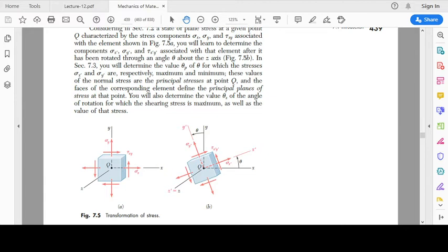In chapter 2 we talked about axial loading, in which the loading was in one direction only, but now we are going to have loading in say 2 or 3 different directions. So we are going to have normal stress sigma x, normal stress sigma y, and if we are talking of 3D, then we will have normal stress in z direction also, which is going to be sigma z. However, we will be restricting our study to 2 dimensions only, so we will be talking about biaxial loading. So we will have sigma x and sigma y.